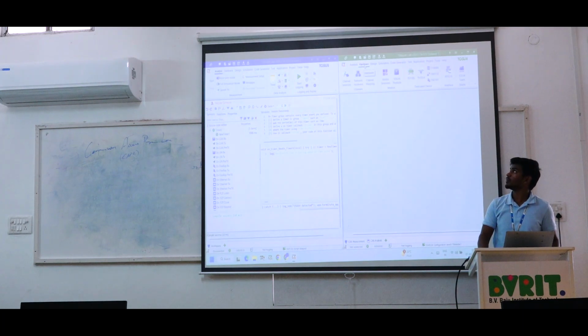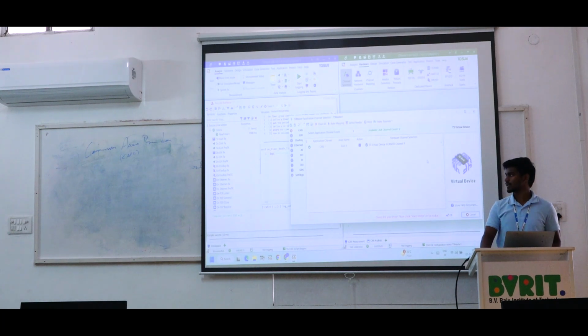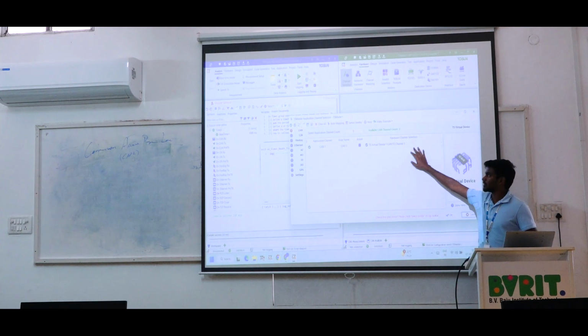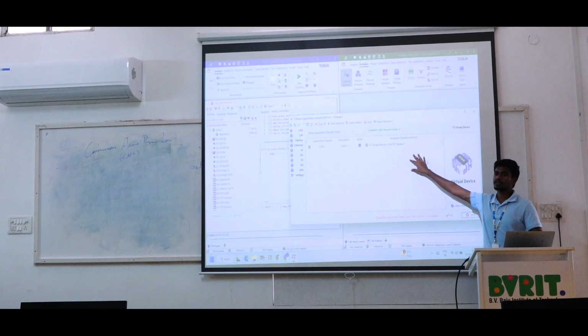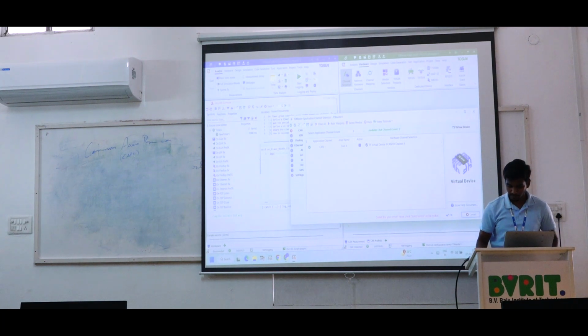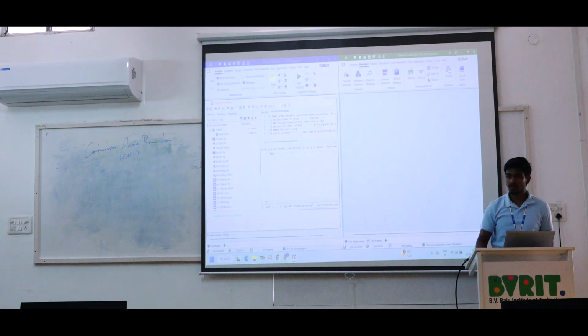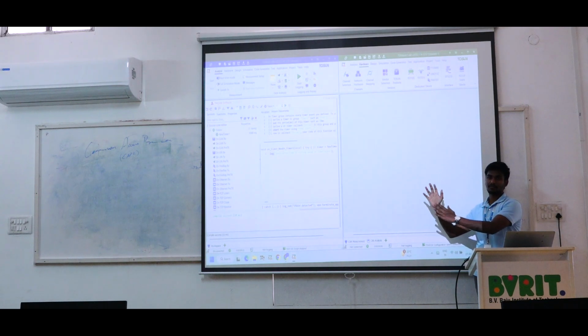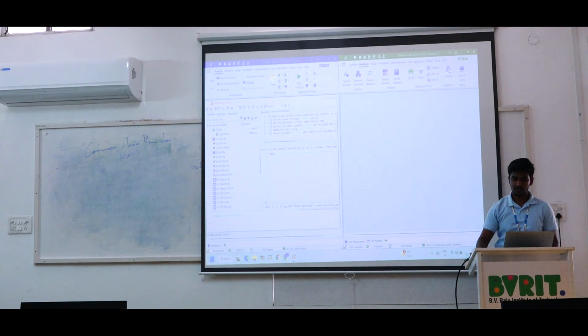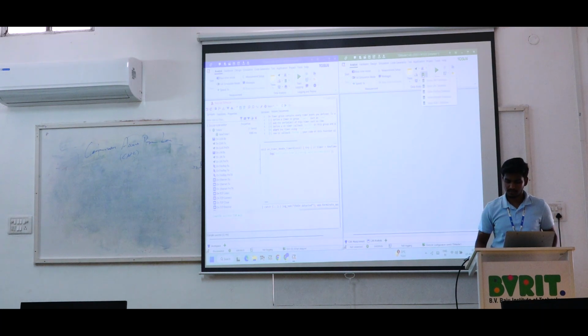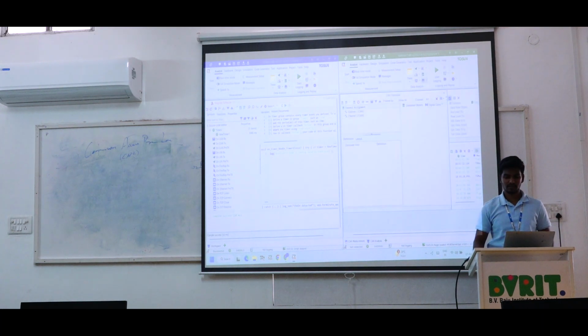Go to hardware at the top. After analysis you have the hardware. Just select the channel selection, so it is asking for the channel. In the previous tab you also took the same virtual device. Please ensure the same virtual device is selected, and click OK. Now these two tabs are interconnected based on the virtual devices. Next you go to analysis and then please upload your database. In this new tab, we load the CAN database.